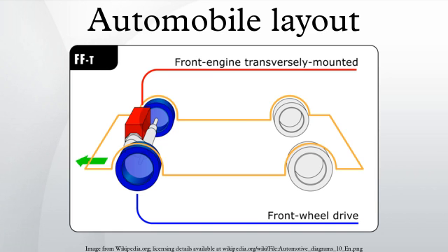Improved drivetrain efficiency. The direct connection between engine and transaxle reduces the mass and mechanical inertia of the drivetrain compared to a rear-wheel drive vehicle with a similar engine and transmission, allowing greater fuel economy. Assembly efficiency. The powertrain can often be assembled and installed as a unit, which allows more efficient production. Placing the mass of the drivetrain over the driven wheels moves the center of gravity farther forward than a comparable rear-wheel drive layout, improving traction and directional stability on wet, snowy, or icy surfaces.